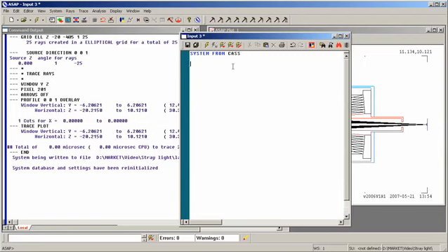Here we go. The object of interest is called conbaff.inside, meaning conical baffle, interior surface. I merely issue the command object conbaff.inside, which tells ASAP this is the object that I want to modify. I'm going to enter a very simple model. I'm going to assume that the scatter property is Lambertian, that is to say, the scatter characteristics, or BRDF, bidirectional reflectance distribution function, is constant as a function of incident and scatter angle.